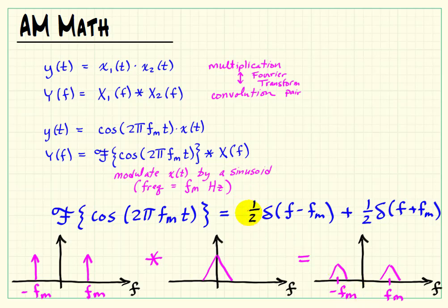And again, if we started out with an original amplitude of 1 on our source signal, then when we split it in half and translate it in either direction, we also have to divide the amplitude by 2.